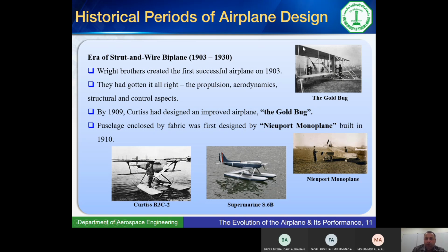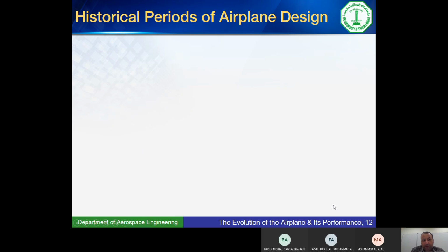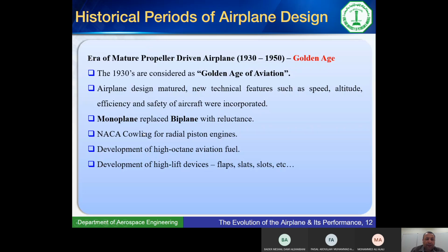Not only this, by having 2 wings, one on top of the other, and connecting them with the struts, we are basically making something like a box, which is stronger. So aircraft started as biplanes because of structural issues. They had a stronger structure, and we didn't have strong materials that could make a monoplane. With improvements in materials between the 2 world wars, aluminum alloys started to evolve, allowing the introduction of monoplanes. Not only aluminum alloy, even improvements in designs of wooden structures made the use of monoplanes possible.